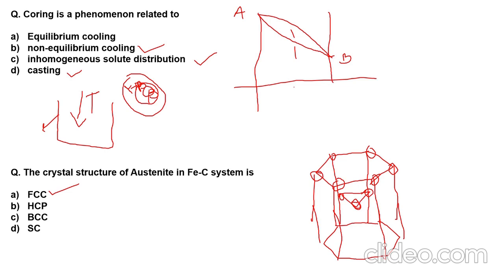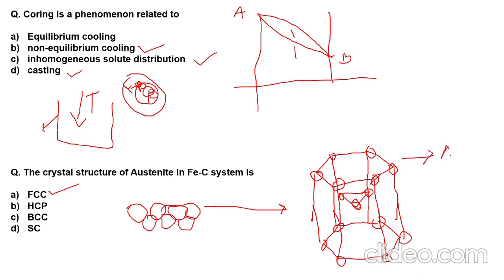These are actually the arrangement of atoms, because when you see the arrangement of atoms in a 3D lattice, you are actually seeing a magnified view of the atoms which are arranged like this, right? So you have a planar hexagon which has six atoms, and then you also have a plane at the bottom which has six atoms. So the plane at the top and the plane at the bottom have the same arrangement of atoms. The stacking is the same, so this stacking of atoms can be referred to as A stacking.